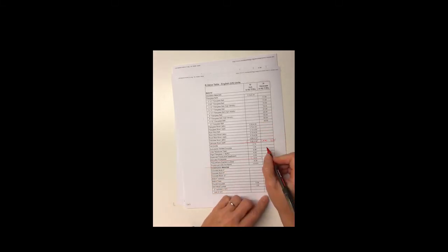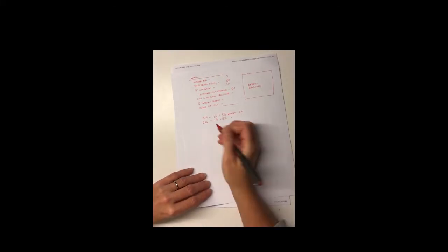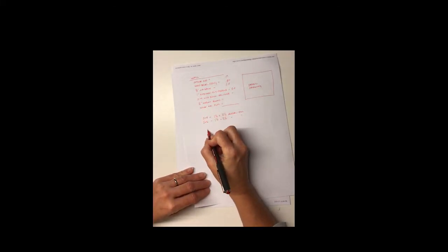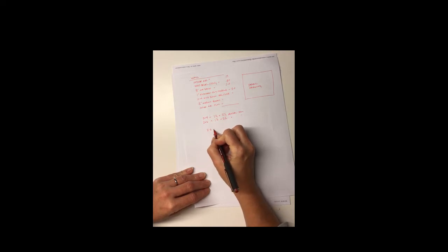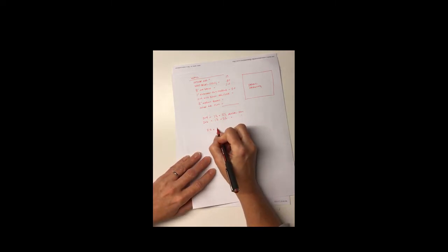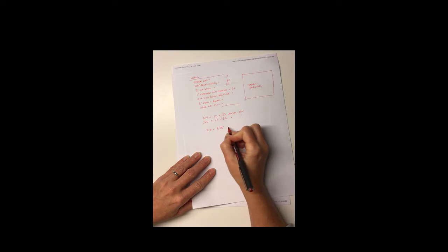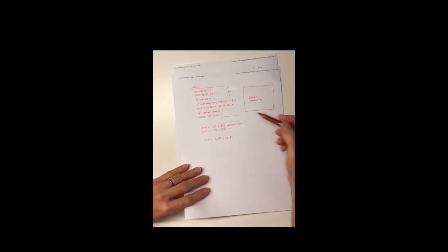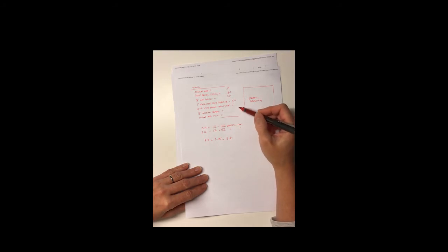So that is per inch, and in this case, I have a 2 by 4, so I have 3.5 times 3.85, and that's going to give me 13.47 for the insulation that's in the cavity.